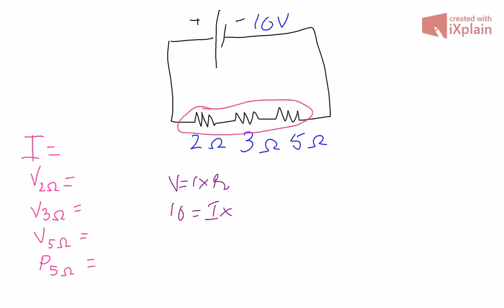If you look at each of these resistances, they are all in series. The way we can find out a resistor is in series is if there is no division between the 2 resistors. This line right here feeds from one resistor to another, but if the resistance looks something like this, we know for a fact that this is no longer a series resistance. So this is just a quick way for you to figure out whether the resistors are in series or they're not in series.